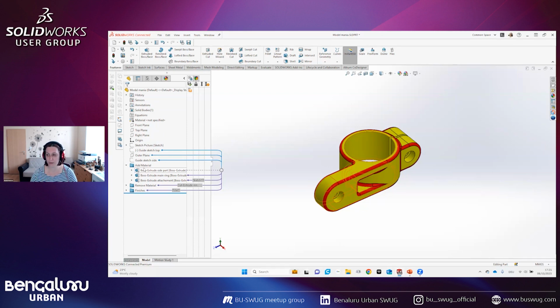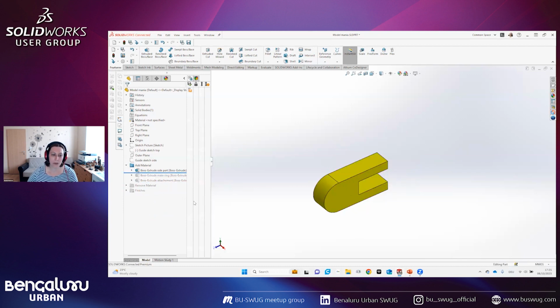First I have a folder which is the base panel. After that, a folder for cut out for the connectors. After that, another folder for the plating. And then a folder for engraving, because this panel has a lot of steps. But with something simpler like this, I'm just using different folders which are add material, remove material, and finishes. And now we will go step by step.